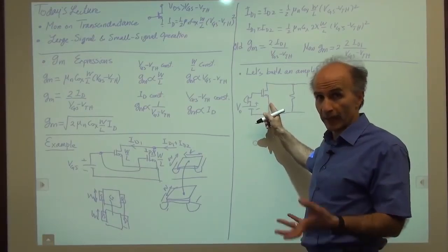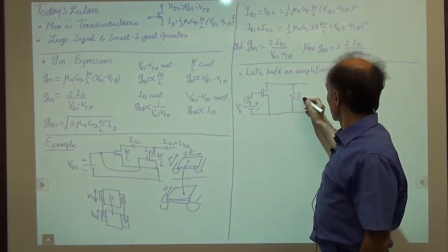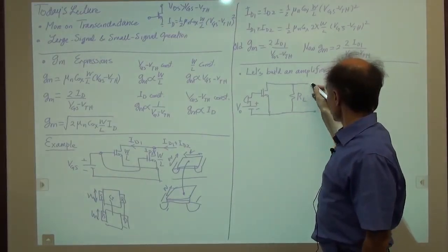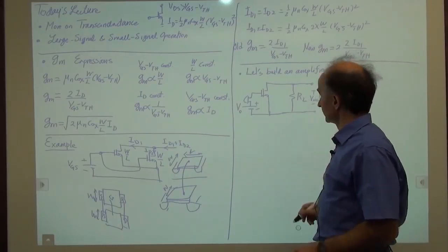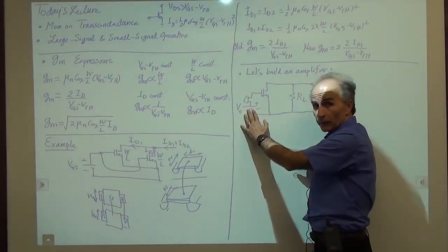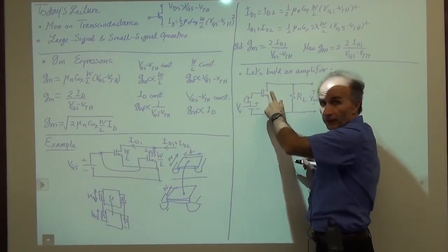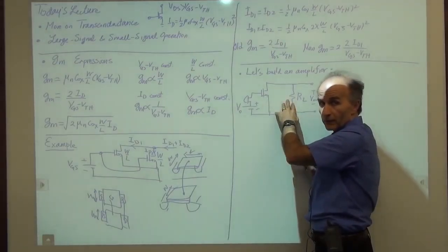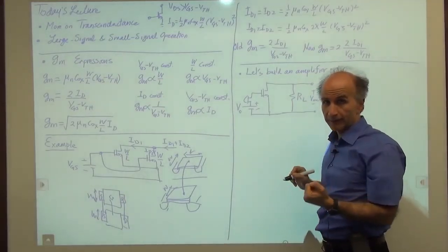We usually like voltages as outputs and maybe even inputs. So we pass it through a resistor. And we said, this is our output voltage. So if the microphone signal is superimposed on a voltage, when the microphone signal changes, it wiggles, the current changes, the changing current flows to this resistor, this voltage changes, and that's the amplified microphone signal.